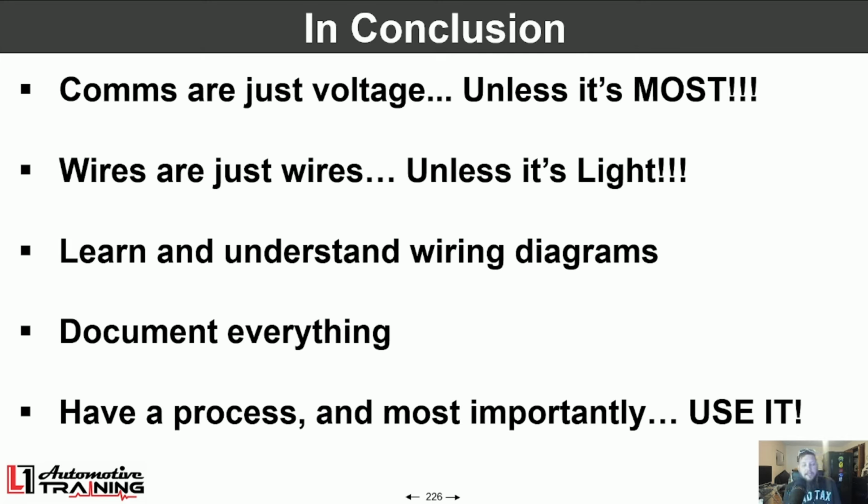So, when we get to communication faults, comms are just voltage, unless it's MOST bus. Wires are just wires, unless it's fiber optic and it's light, of course. And the biggest part here to leverage is understanding the network architecture and wiring diagrams. Also, documenting every single thing you do is super powerful.